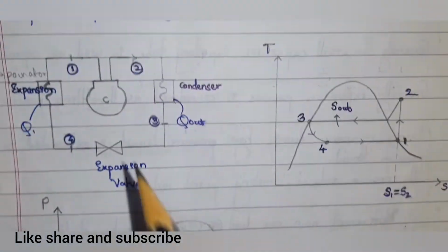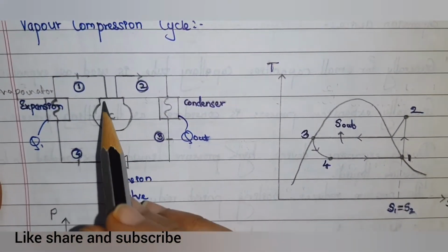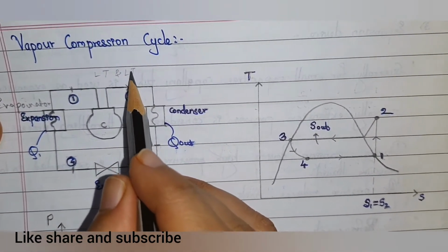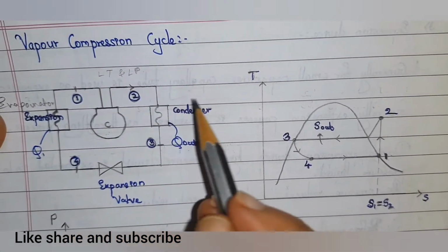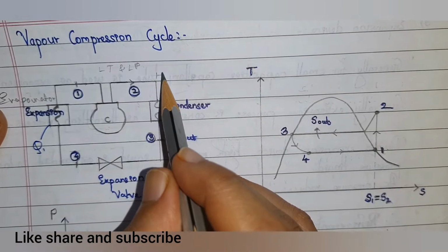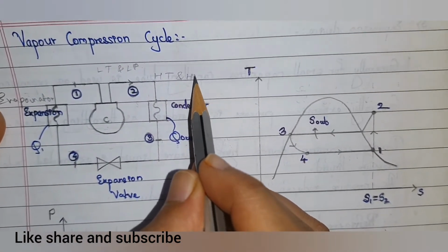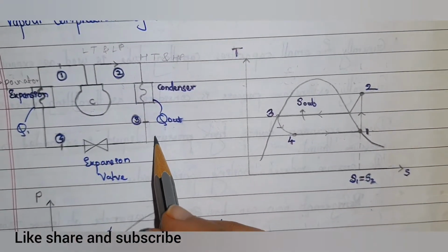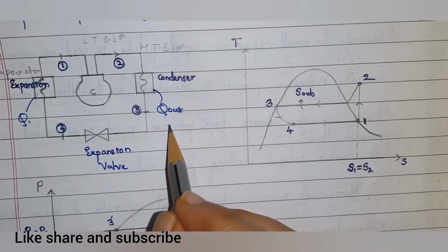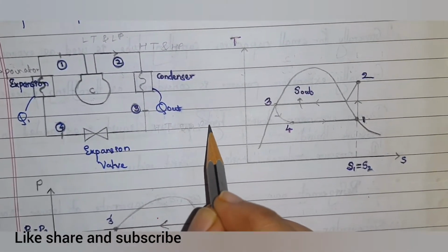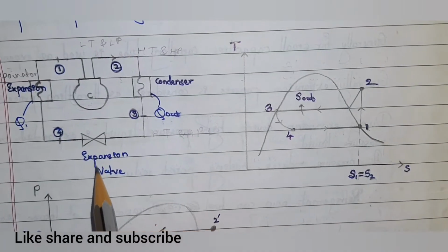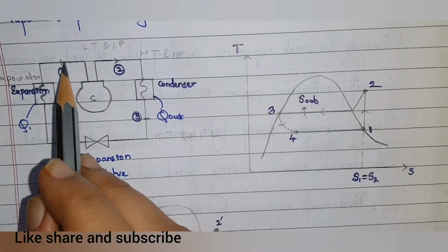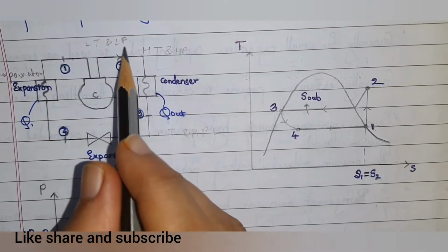So see, the compressor compresses low temperature and low pressure vapor and transfers it to the condenser by converting it into high temperature and high pressure vapors, and this condenser liquefies and converts this into high temperature and high pressure liquids, and after the expansion valve they go to the evaporator and are again converted into low temperature and low pressure.